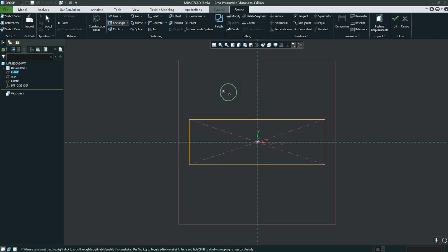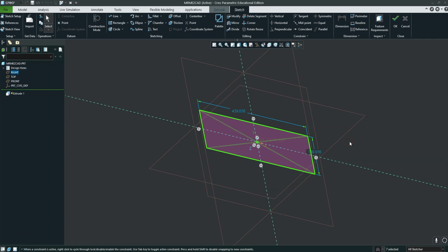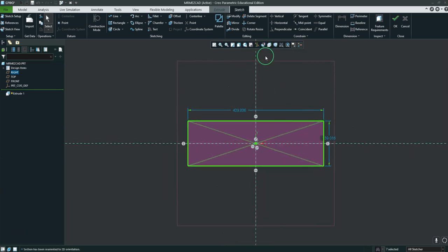And then I'm going to show you two ways that you can exit a command if you haven't used Creo before. The first way would be coming up and hitting this arrow, which will work. The other way that I like to use, because it makes me not have to move my mouse as much, is if you click your middle mouse button. Just click it, the point should disappear, and you should see dimensions pop up. Now, if they don't pop up, that means you held it for a second. So just click it, and then come back up here and hit the sketch view button. That happens a lot to my students because I'm asking them to use a really complicated program like Creo before they've ever used a parametric modeling program.